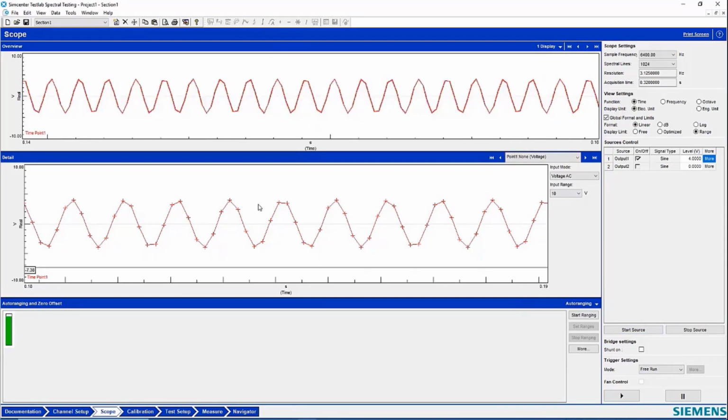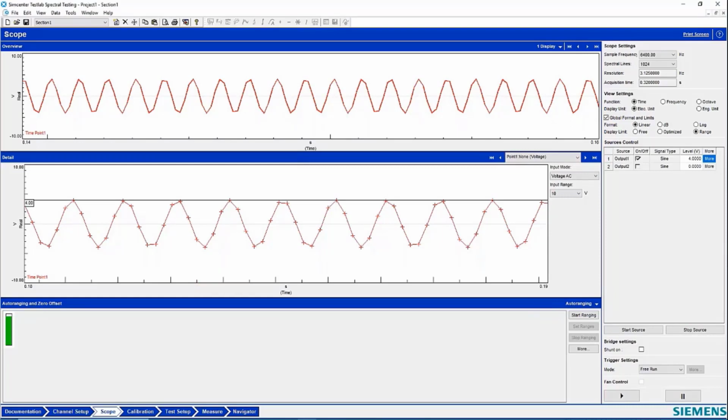Yeah, a little jagged. And you can kind of see now the odds that I have a sample hitting on the right peak, I move this to 4 volts, it's a bit less sometimes. I don't quite hit the peak. Yeah, sampling 6.4 times the highest frequency of interest, I'm going to be off on the amplitude, at least as I view it from the time domain.